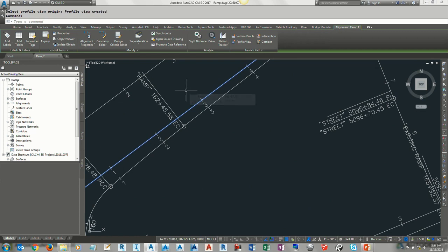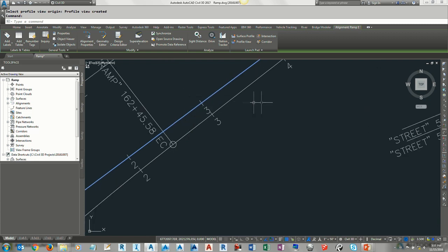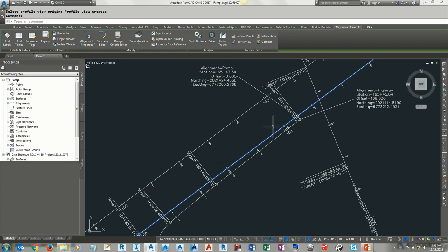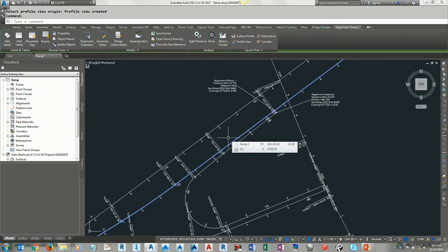This CD1 is actually the left edge of travel way of this ramp. It's 12 feet wide. So at 12 feet, 2% cross slope, the D2 point at the end, you can calculate is going to be subtracted. You can calculate 12 feet minus 2%, you get the elevation of this, and that's going to match up to the grade at the end of this, and that grade, I already know it, we figured it out, it's 1.13.